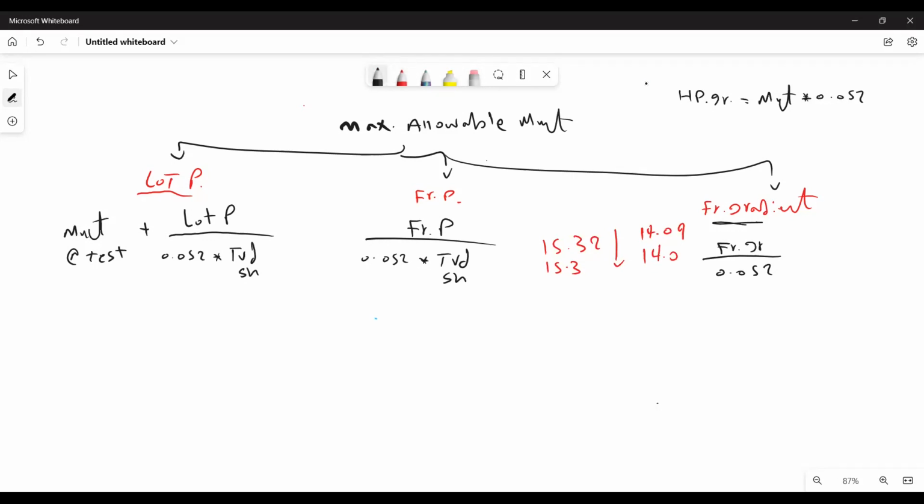Second thing to calculate is the MAASP. Maximum allowable annular surface pressure equals what? Equals fracture pressure minus hydrostatic pressure at the shoe. Okay, so if we make the composition for the two factors here, it will be the maximum allowable mud weight, the one we just calculated, times TVD shoe times 0.052.